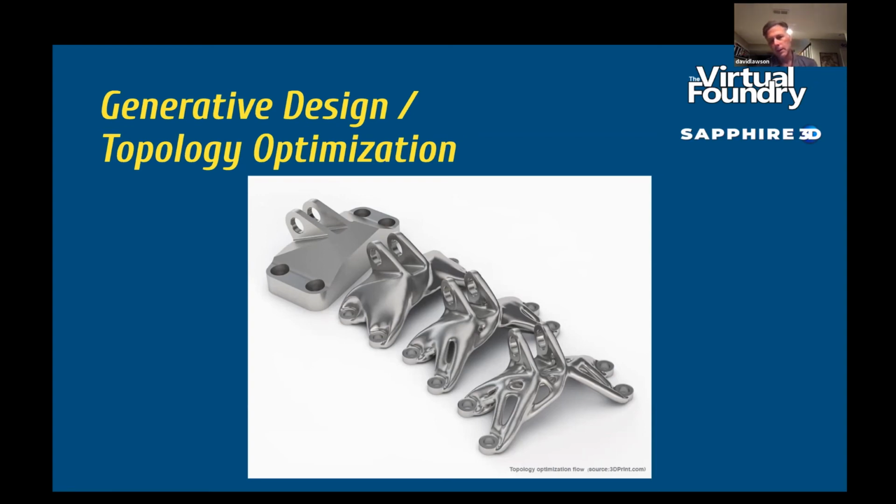You look at the part at the end of the generation there, and my experience with those types of parts is they can sinter very consistently, especially when you start to put in these circular tubes and rods and things like that, those sinter really well. So it's definitely where the industry is headed anyway. Just like you said, it's needed from a design standpoint, and also for material savings and things like that, but it goes along with the sintering process really well.